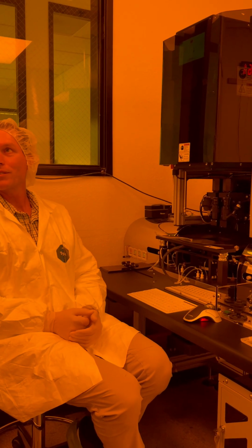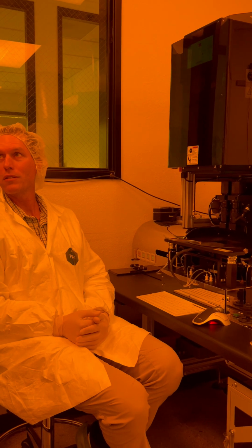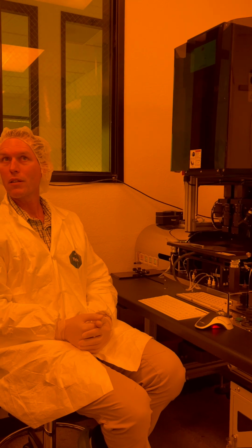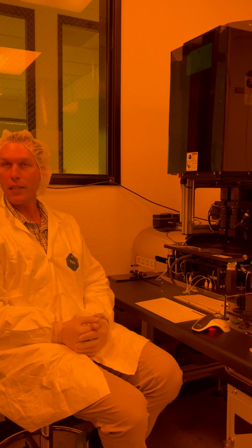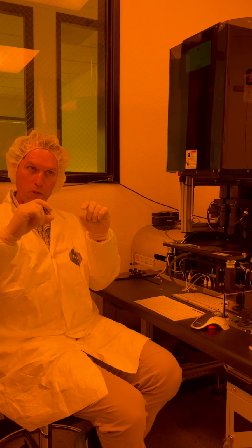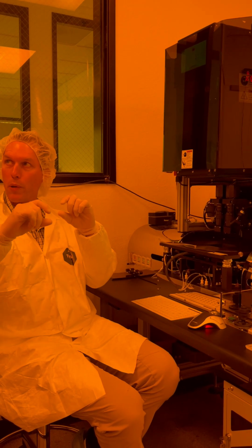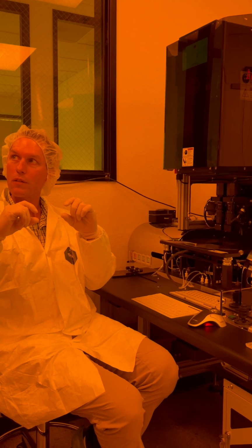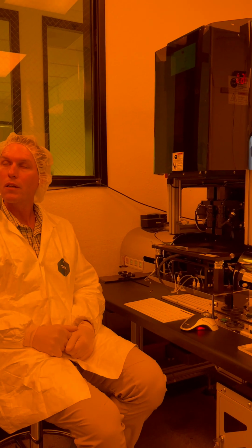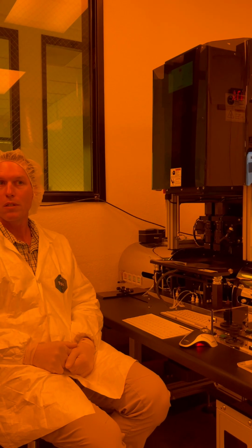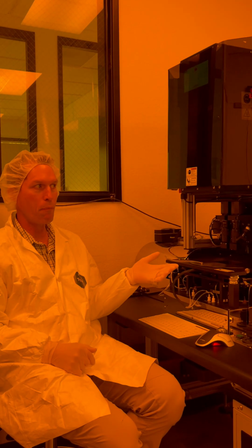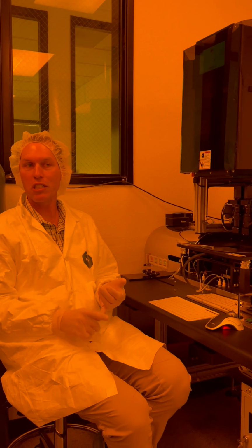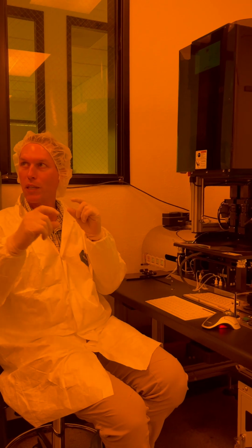So you actually do have bearings on the top of the wafer right now? Is it contacting the wafer? Yes, those three balls, there's three stainless steel balls, those three points touch the wafer. And you don't see any weird issues from that? No. I mean, in most contact aligners, this is how it's done. EVG, SUSS, they all use three spacers.